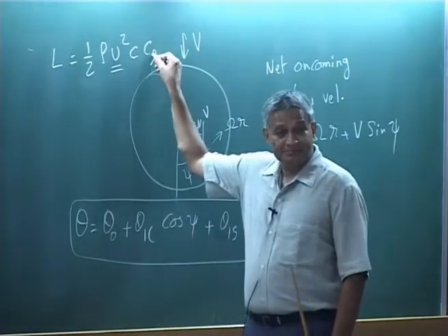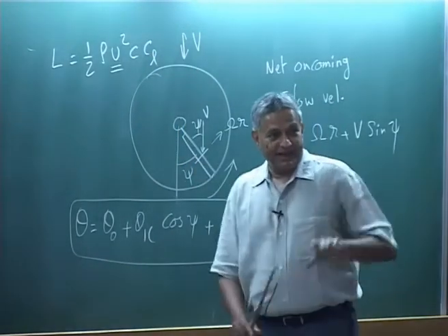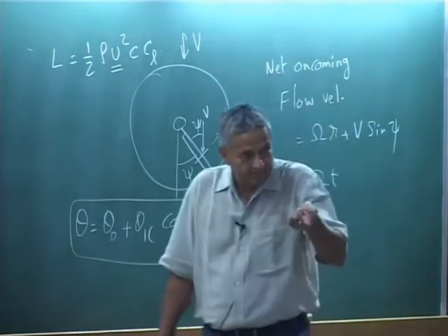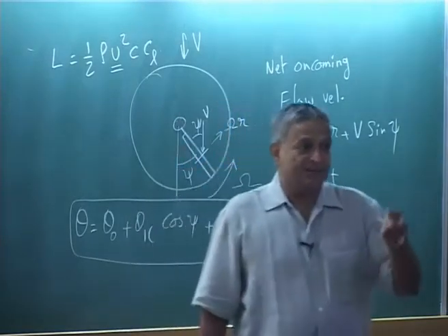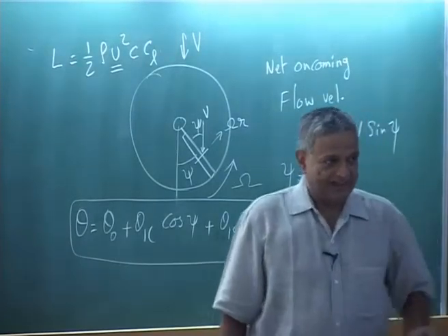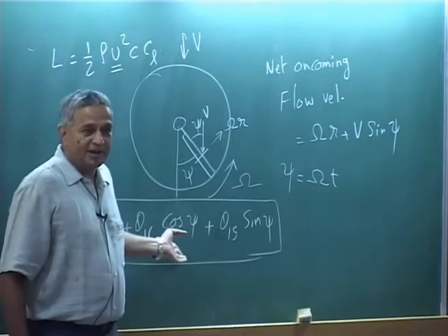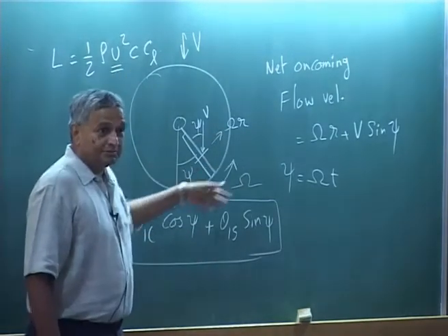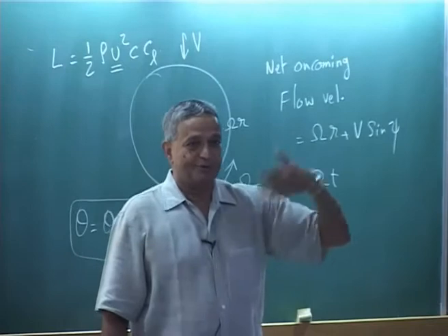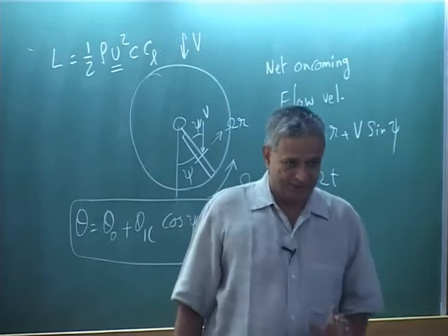Lift curve slope into angle of attack. The angle of attack has this as a component. That means C_L is also time varying. You see, now C_L will have, if you simplistically say, this one harmonic. Now, U square too, you multiply, you will have higher harmonics, more and more. So, you will have more and more components coming in, you follow.